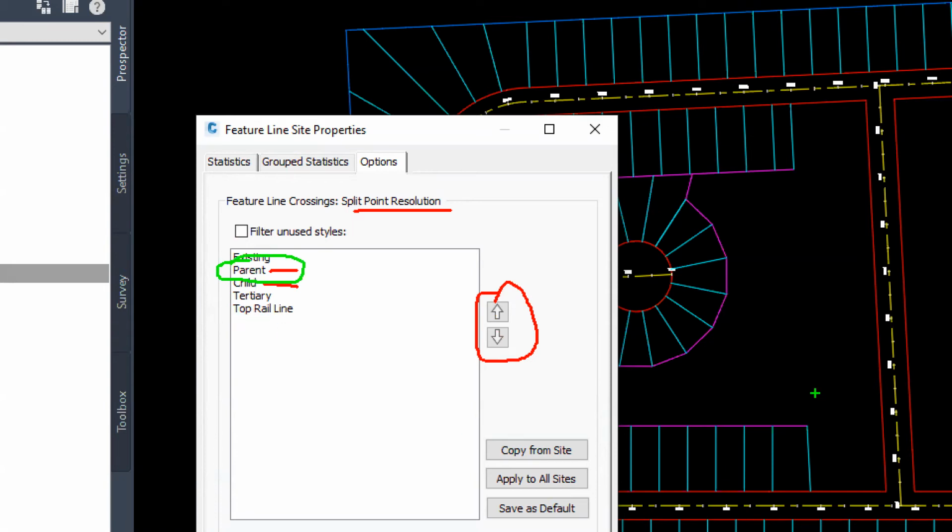So in our site grading workflow, this is places where we can define an ADA ramp. This is places where we can define the site grid lines or our gutter lines. Things that have more importance are going to get this higher style because we don't want to accidentally overwrite them. Other feature lines, maybe we're just adding these for extra TIN definition, or we want some more labels put down in our drawing. These tertiaries are basically going to function as read only.